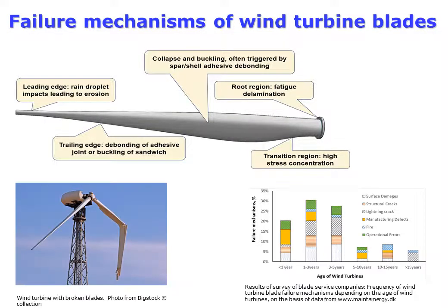How and why the wind turbine blades fail. Wind turbine blades are subject to complex environmental and mechanical loading during their service time. But they can also fail due to extraordinary events like transportation damage, lightning strikes, bird impact. Several regions of blades are especially susceptible to degradation during service time. Leading edges of blades are subject to rain and hail erosion.